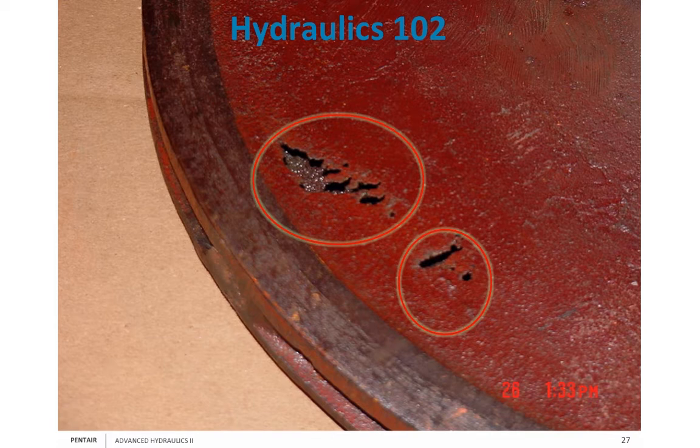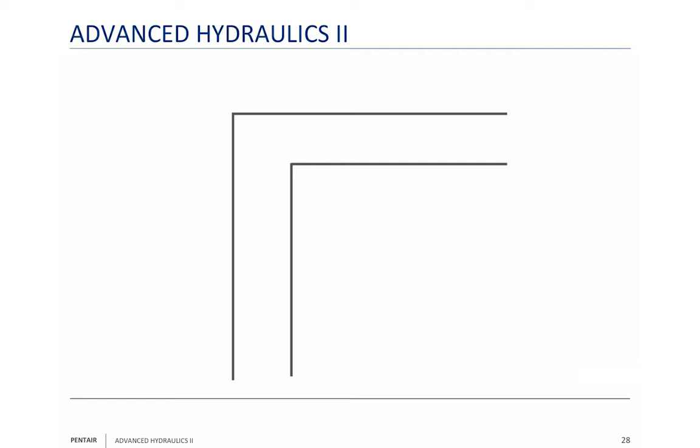And he says, I don't care. I would rather have the flow. So that's the cavitation damage right there. It can be prevented. That's the important thing to remember. You can always prevent cavitation just by putting more back pressure on the pump.